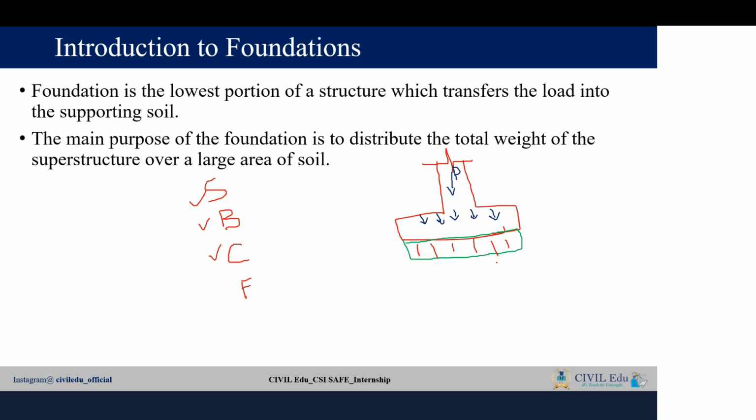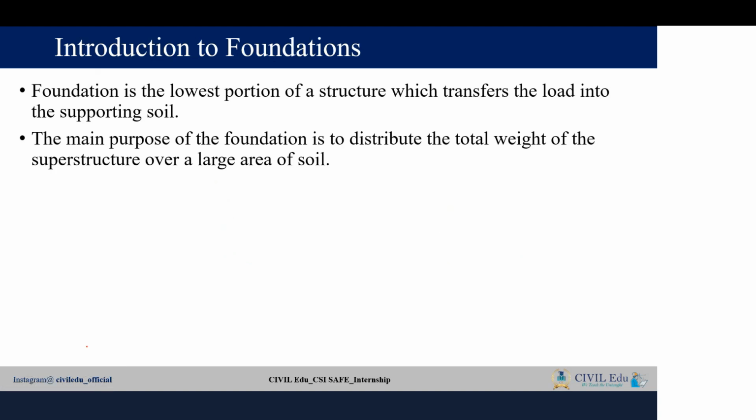Even when we are designing the foundation in the manual calculation as well as in the CSI SAFE software, we are going to design the foundation not to carry the load, but to distribute the load. That's the whole purpose of any structural element, not just the foundation. Even if you take slabs, beams, columns, and footings, you don't design them to carry the load. You design the members to distribute the loads equally to the next layer of the structural element.